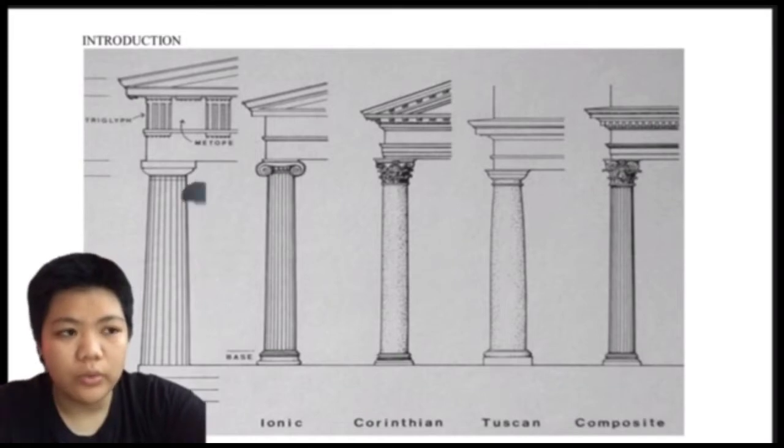A small wooden or metal shaft is normally called a post, and supports with a rectangular or other non-round section are typically called piers. For the purpose of wind or seismic design, columns might be intended to resist lateral forces. Other compression members are frequently named columns due to the similar compression condition. Columns are frequently used to support a beam or arch on which the upper parts of a wall or roof rest.